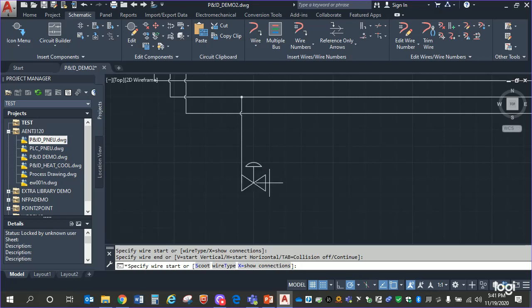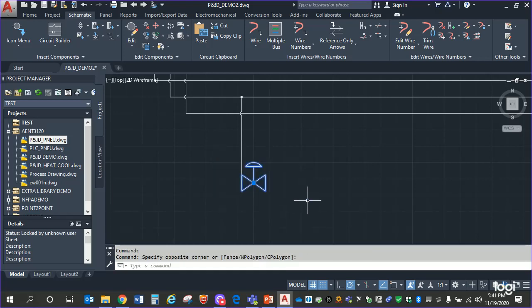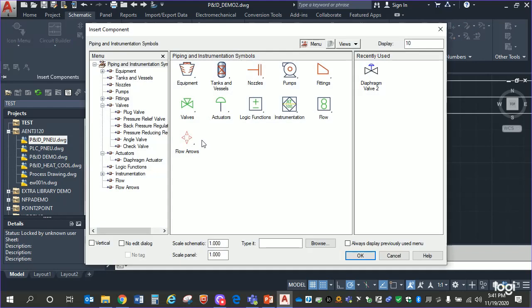Yeah, you know the other thing we can do, let's do this real quick. Select vertical. Yeah, how'd you do that? On that screen there's a bottom, no, you can select vertical when you select a component. Oh, can you? Yeah. Let's do that. I like that better. Let's grab one there. So we'll go back to the components. We'll go back to P&ID. Bottom left button. You've got to be careful. It'll stay on, so it'll be vertical for everything now.